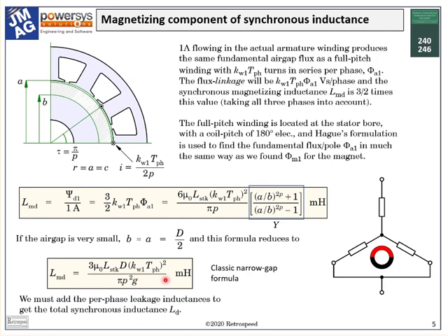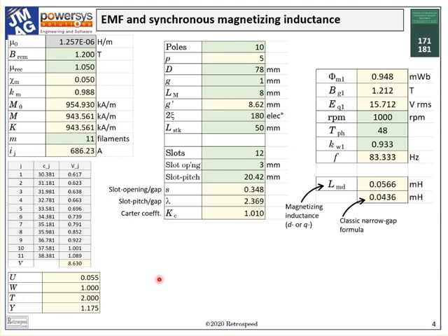TPH is the number of turns in series per phase. And I would say all these items will be thoroughly familiar to any AC motor designer, whether of synchronous machines like this one or of induction motors. So if we go back, we can see the value 43.6 microhenries.